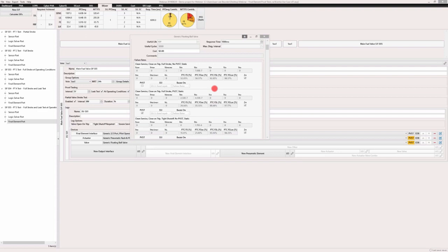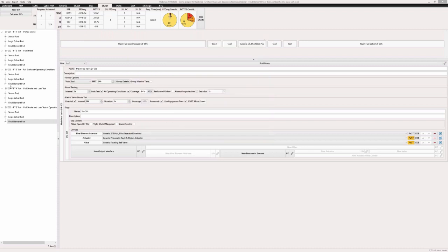But if we look at two different devices, and in this case, yes, it's the same valve, but there's two different operating modes, that doesn't necessarily mean that this higher proof test coverage will lead to a lower probability of failure on demand. But we can see that more failures can be detected, can be revealed if we do this more extensive test. And that kind of makes sense, because now the seats are an issue. So again, knowing the failure modes, we can see what can be revealed by a test and what not.